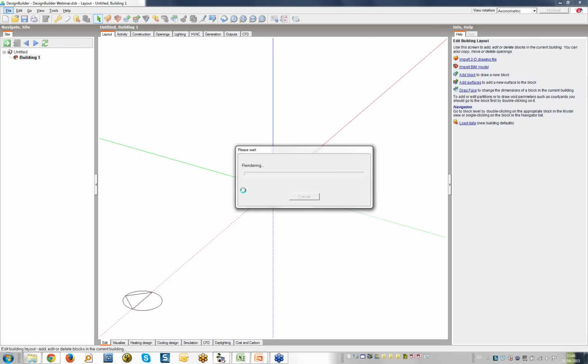It's worth pointing out that if the surfaces in the BIM model entirely enclose the space, DesignBuilder will use those to create the zones where possible. Where surface data in the BIM model is not available, for example when a surface in a zone is incomplete, DesignBuilder can still import the space as defined in the BIM model.